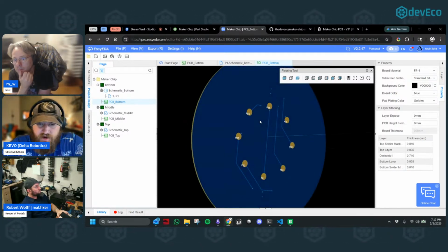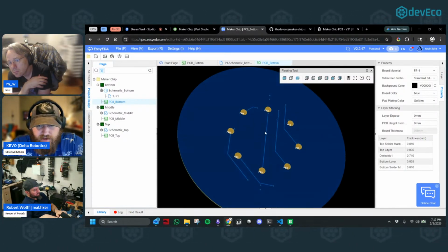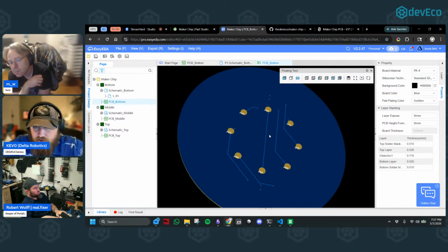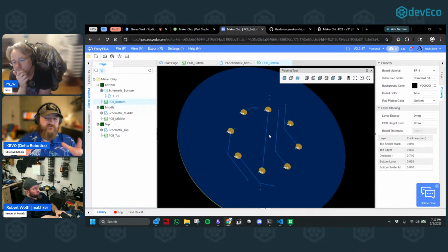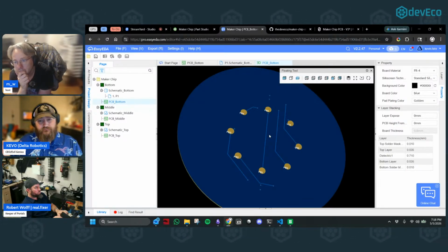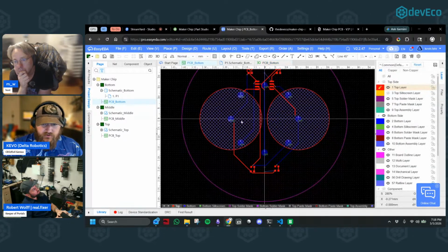Yeah. And at the bottom here, you can actually see the pads. These are the copper pads where the pogo pins would actually interface with a dock. So you have essentially a negative of this design and spring-loaded pogo pins at the bottom. And the magnet, and from this design here, you've got your occlusion zone.